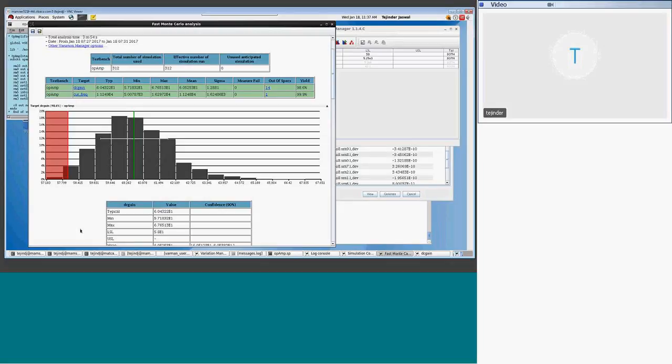You see the shape of your distribution, you see if it's efficient or not, you see the sigma and the mean max. You need to see it as Monte Carlo. It's completely similar, but the main difference is we need many fewer simulations. Now, if you want to study your design to 3 sigma accuracy, you do 1000 Monte Carlo with the fast Monte Carlo